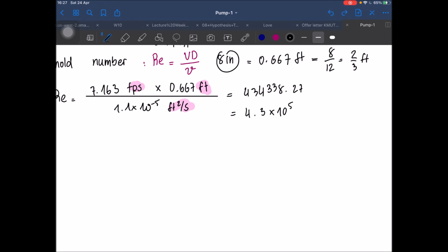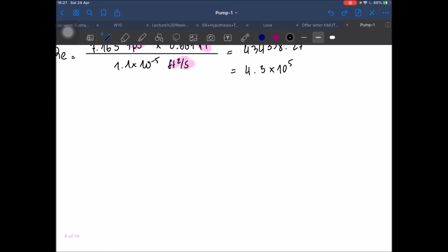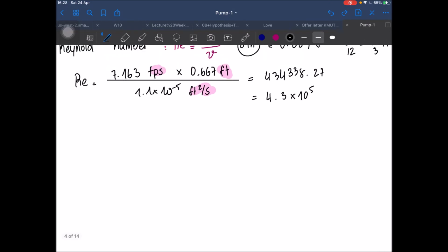Okay. So now we have everything done here. There's no unit here, so we can find Ks over D, which equals 0.0002. And then we have the F, which is the friction. So the friction here equals 0.016. These are the given values, the characteristics of the steel pipe.